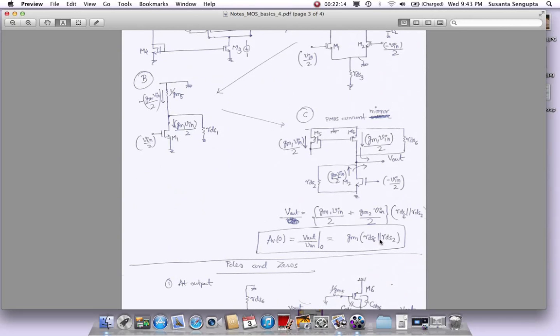And as you work through different kinds of circuits, you would get really good at doing these things of tracing. You have a voltage, how much current is there, what path the current is going to go, what are the different paths, and which is the lowest impedance path, and all that stuff. So we got the DC gain.